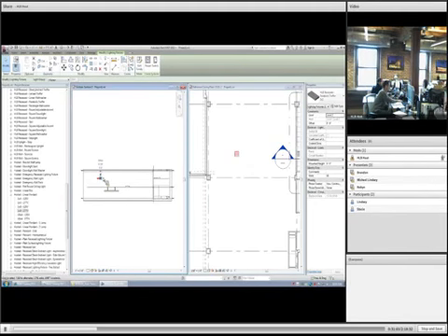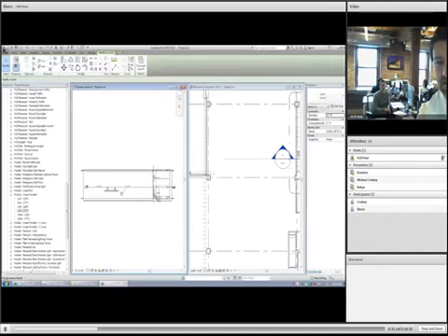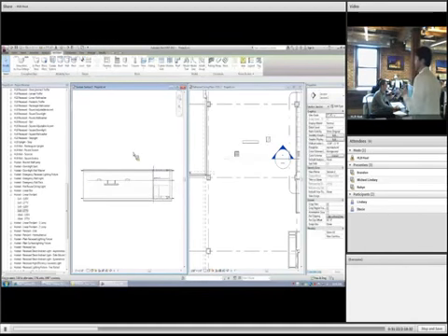But if you locked it, exactly right. So watch this. Align, select the level, then select the fixture, then hit lock. Now you're good. The only issue with doing that is that you'd have to do it for each and every fixture, as opposed to the hosted fixtures, which do it as a group. They'll move naturally with that level as it's going up and down. And you can always unlock something as well.